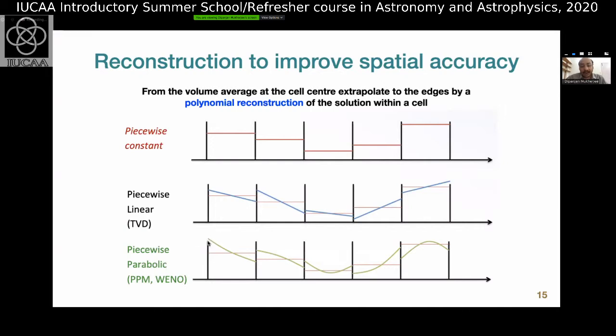Or we can have higher order interpolation schemes. So these are like interpolating between these two interfaces. They're called interpolation schemes. For example, this is third order accurate, the piecewise parabolic, etc. So this is also another level of sophistication we always use, that between these two cell interfaces, we do not assume a constant description of the fluid variable, but it is varying with slope.